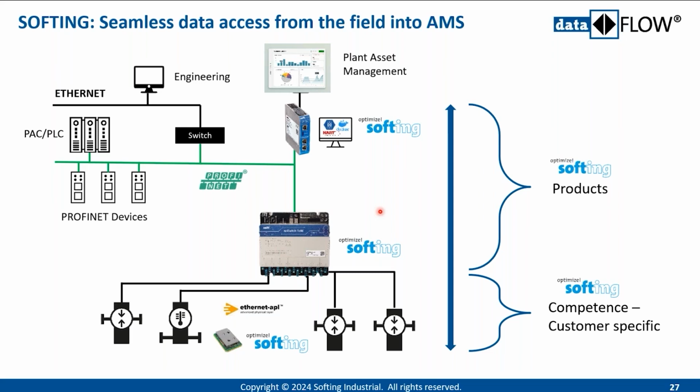Thank you. Another question by Massimo Pagani. Is it possible to interface field devices that work in 4-20 milliampere to an APL switch? If so, how does the interfacing occur? Not really directly. We are looking at some possibilities how to do that. One would be a way of remote I/O access, things like that. I got this request also from 1 or 2 customers who were looking at what the possibilities are, but that would be more of a remote I/O setup, not directly.